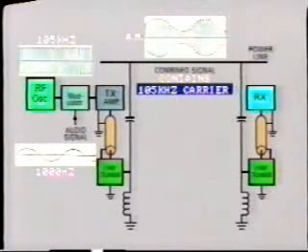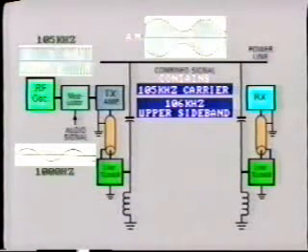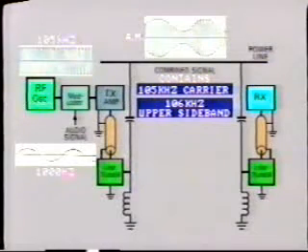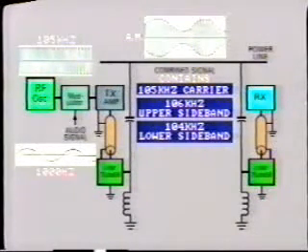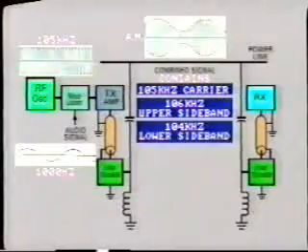The 105 kilohertz carrier is one. Another is the 105 kilohertz plus the audio signal frequency, 1 kilohertz in this example. That is 106 kilohertz. This is known as the upper sideband. In addition to this, there is one more signal, that is 105 kilohertz minus the audio equals 104 kilohertz. This is the lower sideband.